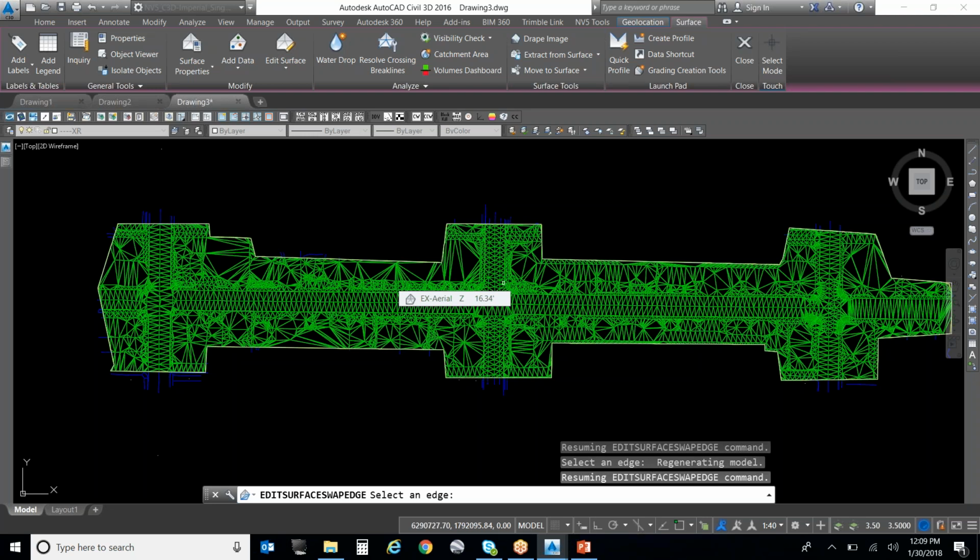Because what happens is you get elevations different by 6 inches and they triangulate to it, and you have these vertical surfaces that show up in your street. When you profile it, you have a profile that does that, okay? So again, keep that in mind.